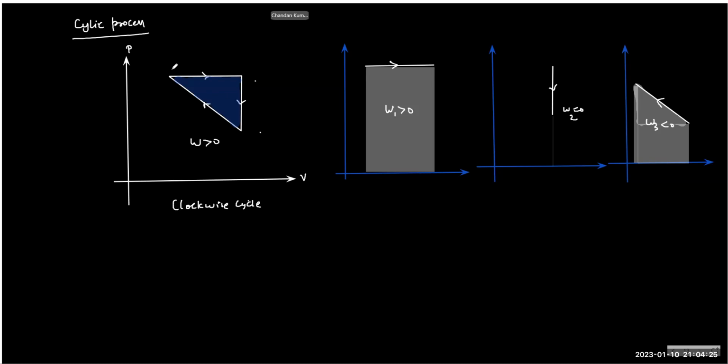Okay, not able to see. This is high pressure expansion and low pressure compression, right? Yes. That's why the work is always positive, because high pressure is deciding the answer. So if you want to just remember the answer, for a clockwise cycle, work we have to take positive. So find the area and take positive value.